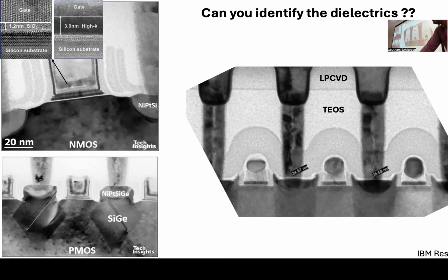When people do the time-dependent dielectric breakdown experiment, they stress the gate dielectric for a long period of time to see when it fails. But they do it accelerated, by temperature and by field. Say your usual operating condition is some electric field E0.